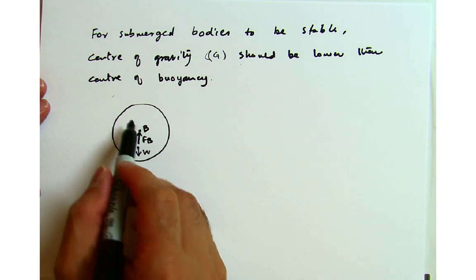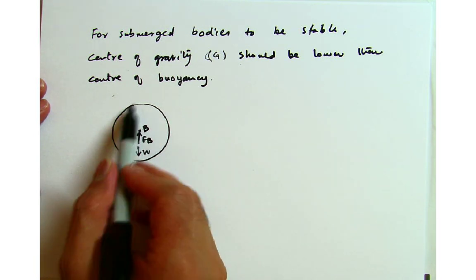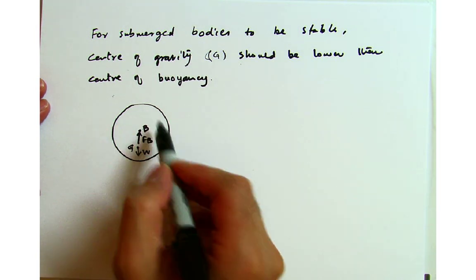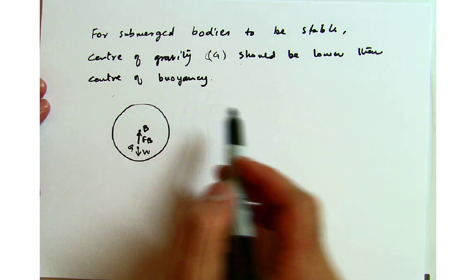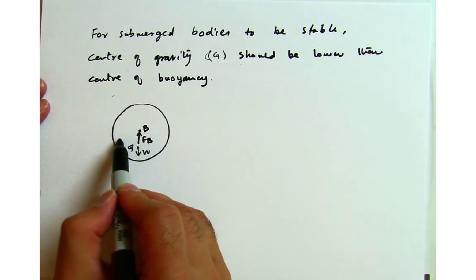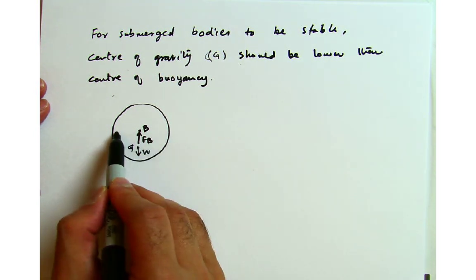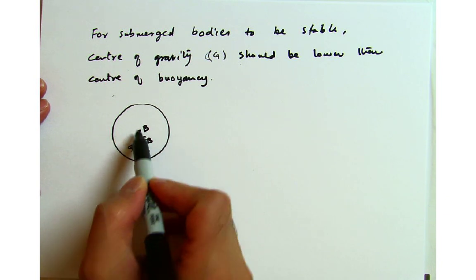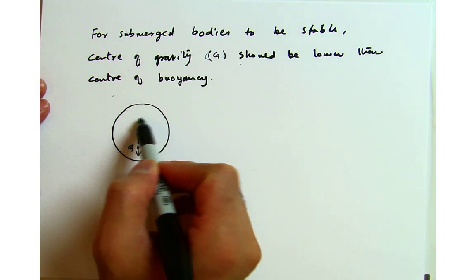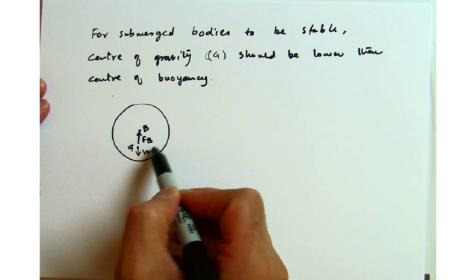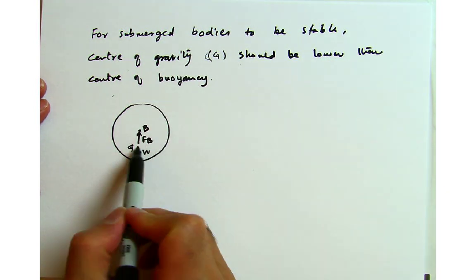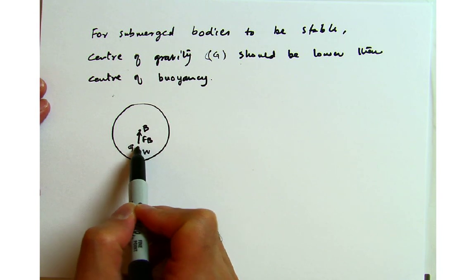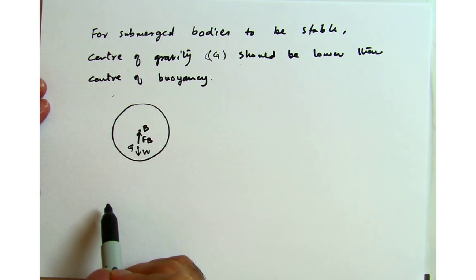So now the idea is the center of buoyancy is the centroid, which is the center of geometry, and the center of gravity is where the whole weight is acting. You can think about it like a submarine, which can have more weight here. If you have more steel here, mostly the weight will be in this area, and if this area is air, that does not contribute to the total weight. That's why the center of gravity can actually be below the center of geometry. So that's why the center of gravity is below B in this case.